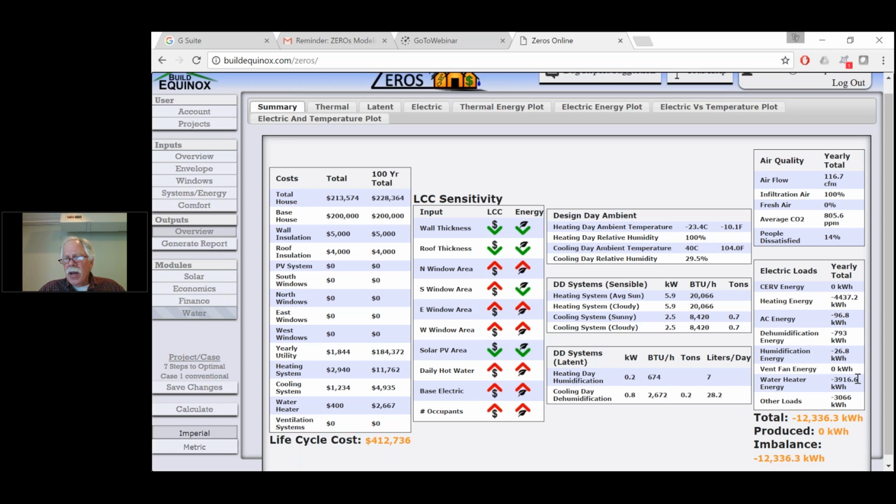Finally, take a look at water heating for 3 people. About 1,000 kilowatt hours per year per person for water heating. That's equivalent to, in this home, what heating energy would be. And then the other loads, 200 watts base load plus 50 watts per person, about 350 watts on average throughout the year. The sum of these two, humans dominate this house, not climate. And that's typical of homes throughout most of North America.